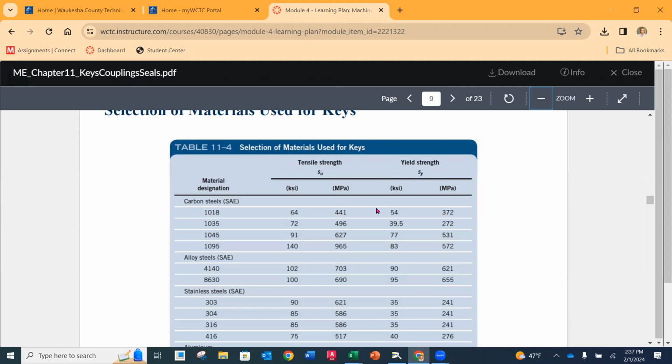And it's considered failure because as you pull that apart a little bit and it doesn't bounce back anymore to its original shape, we've changed the internal grain structure. It's done. It's not going to perform anymore, even if we physically can't see it or it looks like it's still doing okay. Internally, we've changed it and it no longer has those properties that we need. So we always have to be below that yield point when we're designing. So it's important to know that.